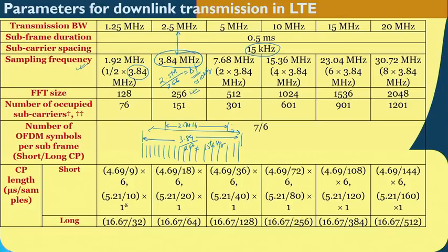But what is done is, at the edge the subcarriers are set equal to 0, they are not allowed to be transmitted. So, if it is 0, then effectively what happens is that one is using only a certain smaller set which fits into this 2.5 megahertz, and then there is a roll off of the spectrum and it dies out by the time 2.5 megahertz finishes.